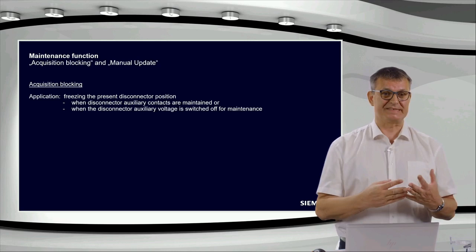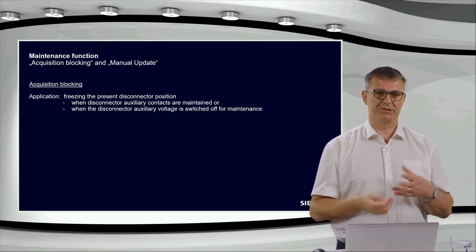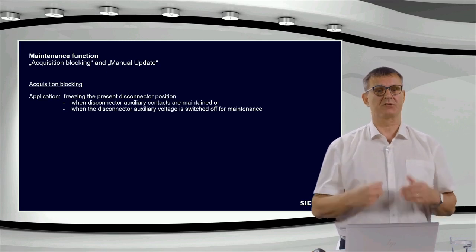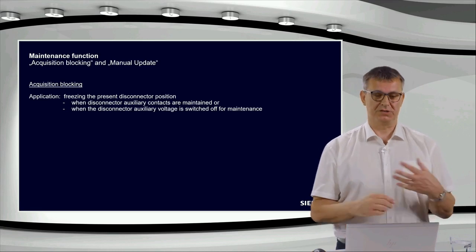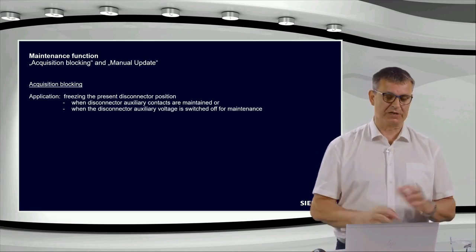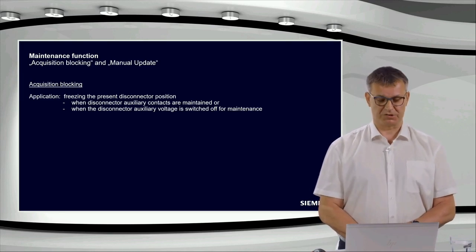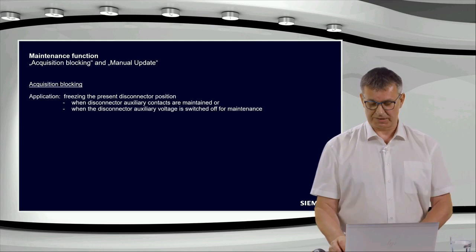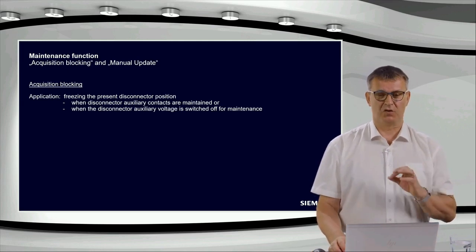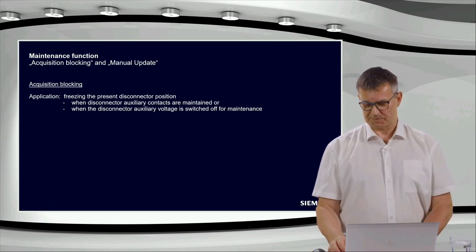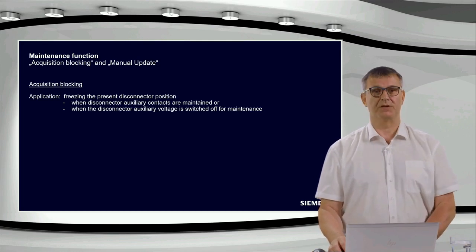Of course, during this time, no primary switching should be done, because otherwise you will get differential current in the selective zones. And the check zone will help you, it will nevertheless protect you against a wrong tripping. But nevertheless, once again, with busbar protection no single fault should lead to a wrong tripping. We want to have 2 security mechanisms to prevent a wrong tripping.